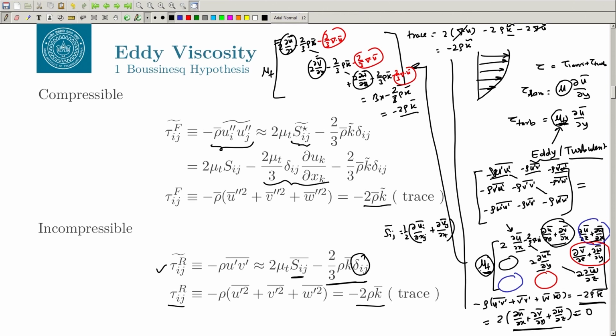That principle is called the Boussinesq hypothesis, as given here, or maybe the Boussinesq model, it was given around 1877, or also called the Boussinesq eddy viscosity model, because we are not basically solving for stress, we are solving for the eddy viscosity. Now, our unknown is nothing but this eddy viscosity, all other things are known, right.